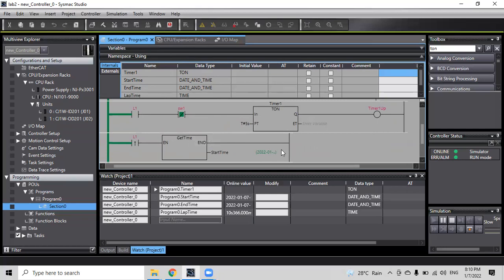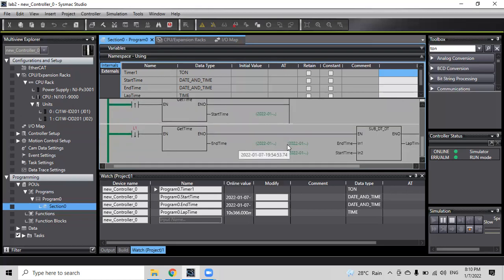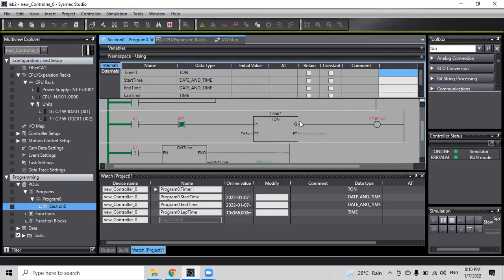All right, so this is the first part of lab 2. You need to be careful, is the letter okay? It's case sensitive. For example, if you define the name in the IO map as a small letter, but in the ladder diagram you give the capital letter, then it won't recognize. So it's case sensitive.